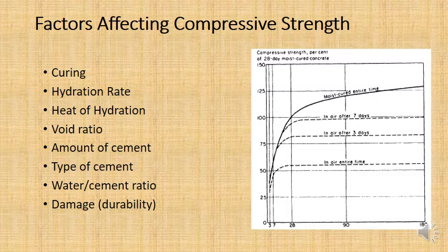If the cement has a lot of air particles that come off the reaction, then those air particles are going to be trapped inside the concrete. Remember, if you look at concrete through a microscope, it will look a little bit like Swiss cheese, where all these channels have formed as air escapes the concrete. And you want to keep that to a minimum for a high strength concrete.